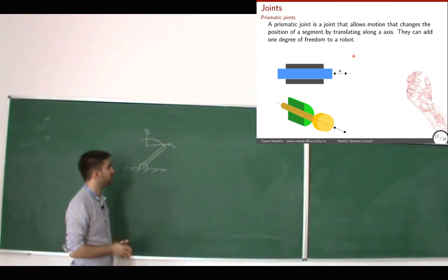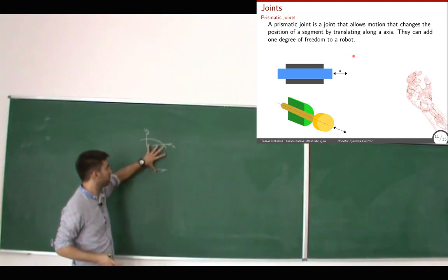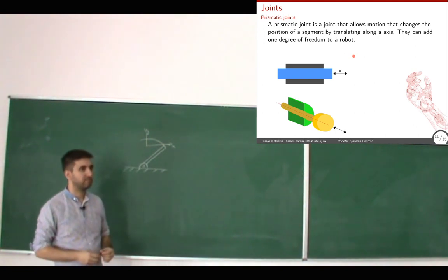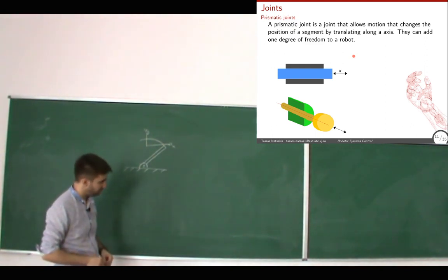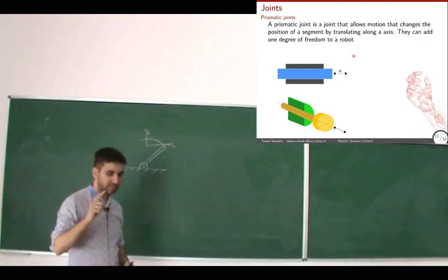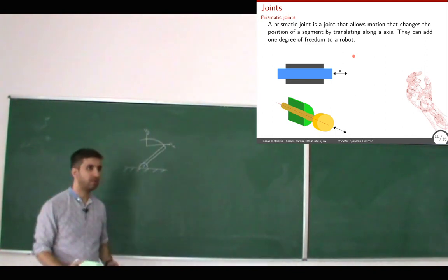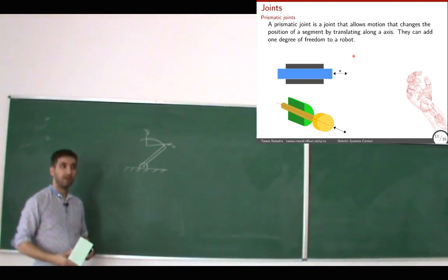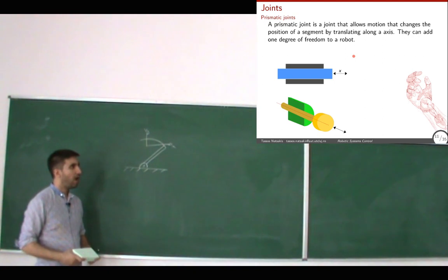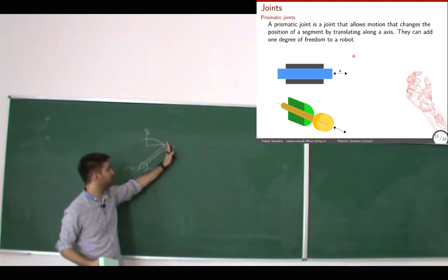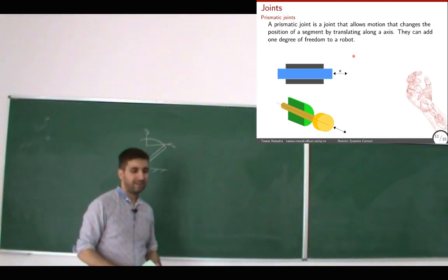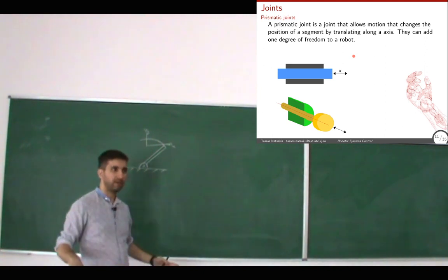Yeah, so that's a good observation. Talking about the robot itself. It's not technically 2 degrees of freedom because the translation movement is not separated from the rotation. Correct. Okay. So that's a good word, separated. Or another way to say it, how many distinct? Or another way to say it, independent. In how many ways can my robot move? Let's say the end effector of the robot, so the final point of the robot. How many coordinates can I change independently?